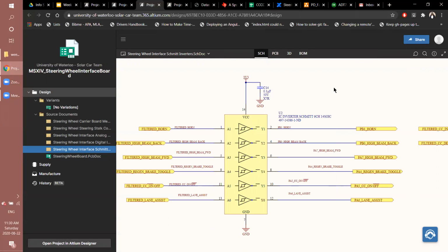Let's just say you have a threshold at 3 volts as your high. So when you have a 3v3 input, you're able to have a logic 1. When you have issues with noise, let's just say that 3v3 input varies between 2.8 and 3.6 because of added noise onto the line.